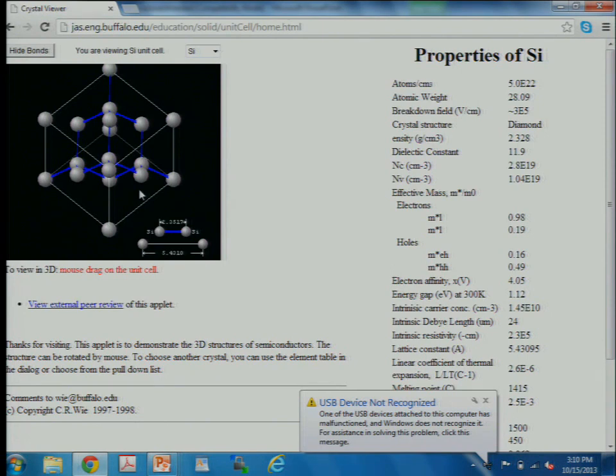Was there a question here? Okay. So that's the fundamental reason. It's not actually atomic density. Atomic density has something partly to do with it, but it's really the bond configuration, physically the bond angles in the 111 plane versus in the 100 and 110 planes. Okay?